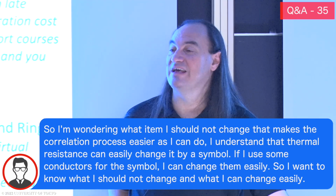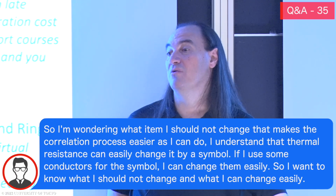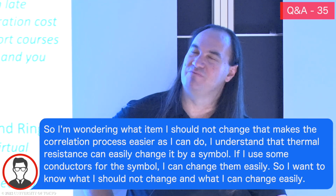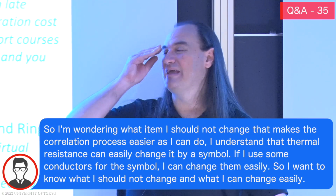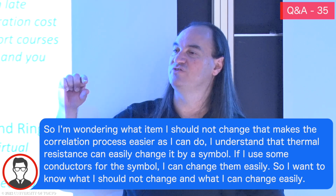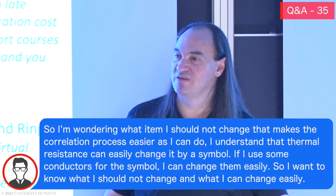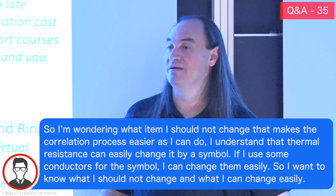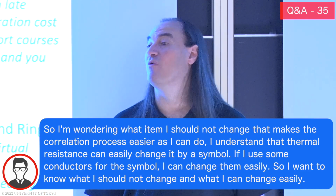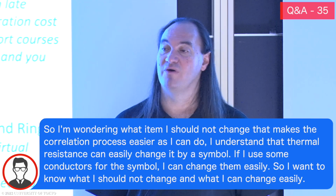But for correlation, there really is no easy way to do it. The best thing you can do before you correlate is get as much data as you can. And then the other piece of advice I have is, keep track of every change that you make, and if possible, only make one change at a time, so that you can see the single impact of each thing. If you change 4 things at once and it improved or degraded, how do you know which of those 4 had the effect? It could be that 3 of them did nothing and one of them was responsible for all of it. So being able to make incremental and step changes is useful.